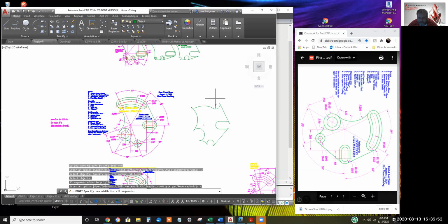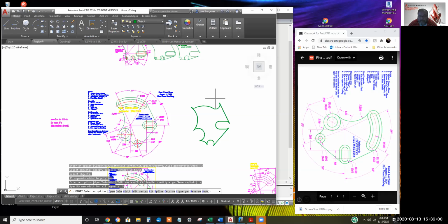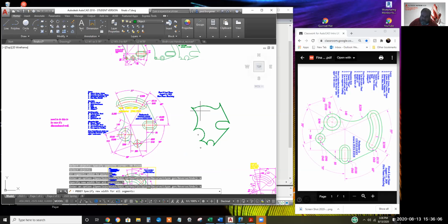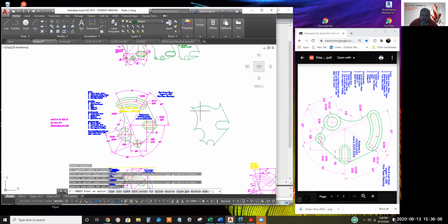Maybe you say a width factor. I'll swell out all the polyline widths so that they're all 5 units wide. There you can see it all swelled up. I can undo or invoke the width option back again just to keep things razor sharp with a 0 width.